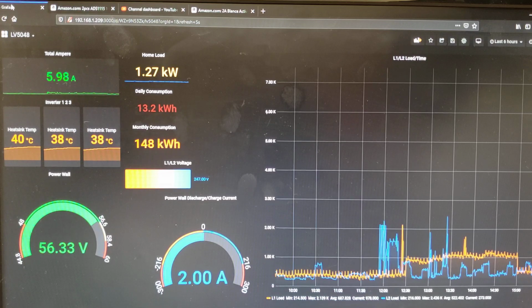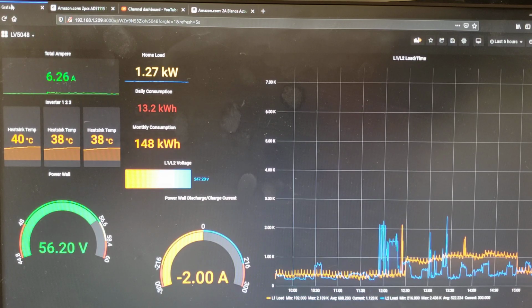I can say that my breaker panel is well balanced. There's not more than one thing that will create a large spike on one of the legs. They're equally divided. Let's say I'm running the dishwasher and the microwave, they are split. They are on different legs of the 240 volt split phase system.